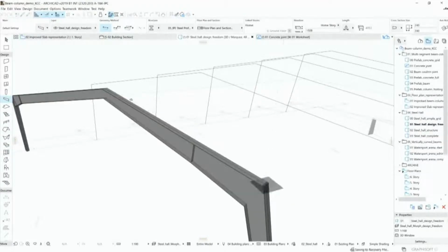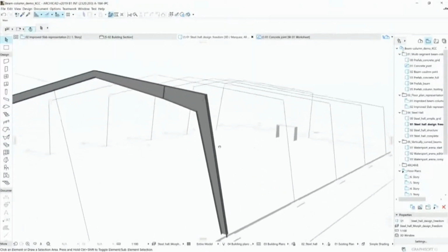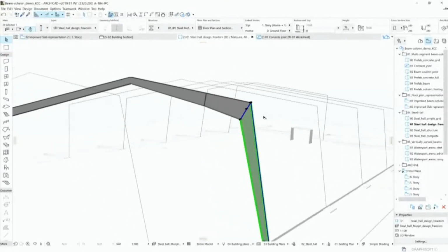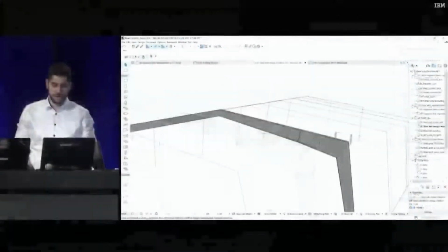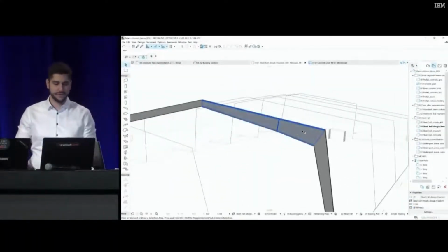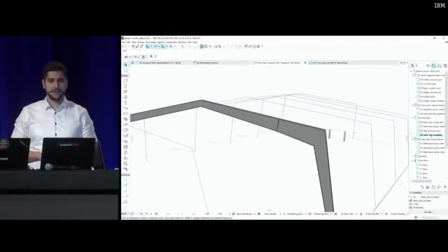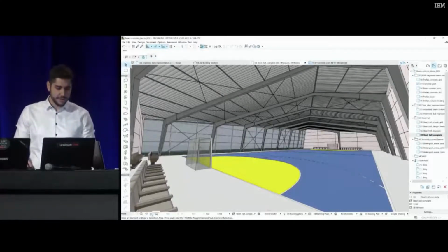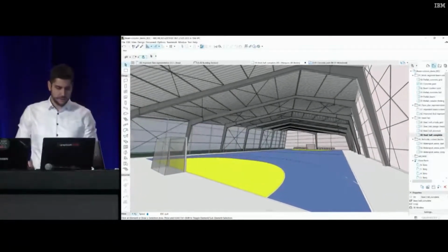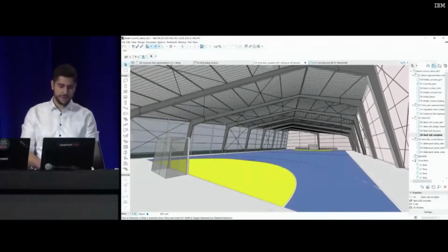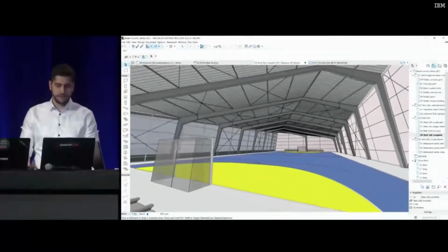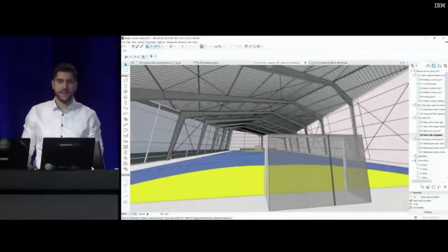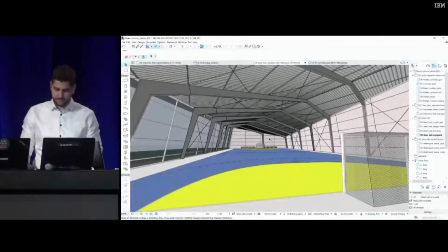representation of such frames. And there's one more thing, that we introduced custom end-cut angles for these columns and beams, so you can have nice and clean connections for your beam column connections, such as this one. Now let's take a look at the inside when the building is done. And similarly to the frames, you can very quickly and very easily model the cross bracing or the purlins of the roof structure, allowing you to work correctly and accurately and still focus on the design.